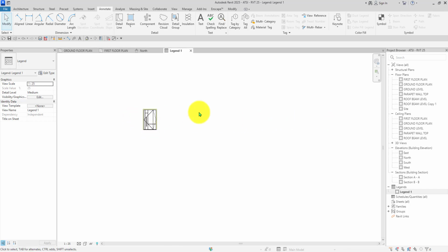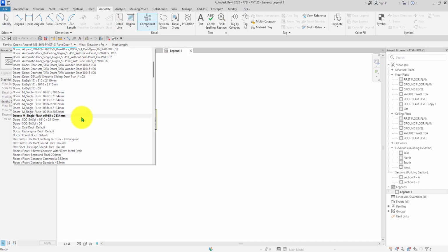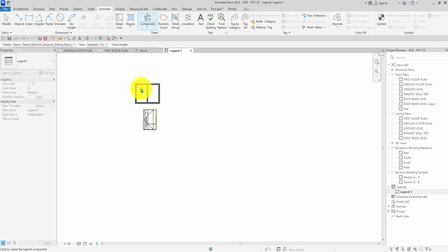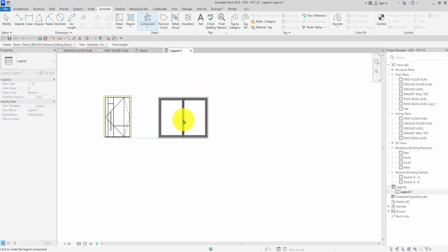I'm going to create like 5 doors in here and also 5 doors beneath. So just head straight into the component tab, click on that drop down menu, and then you click on the legend component. And then let's make sure we find our door 2. Make sure it's in the front elevation. So we have our door 2 in there, and we can just click this in there.